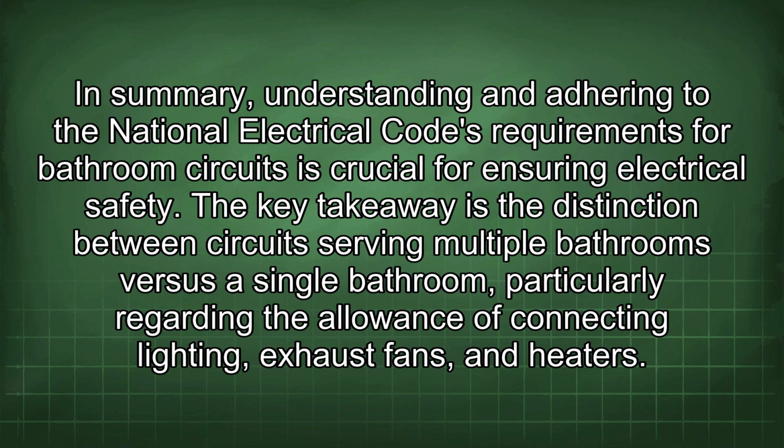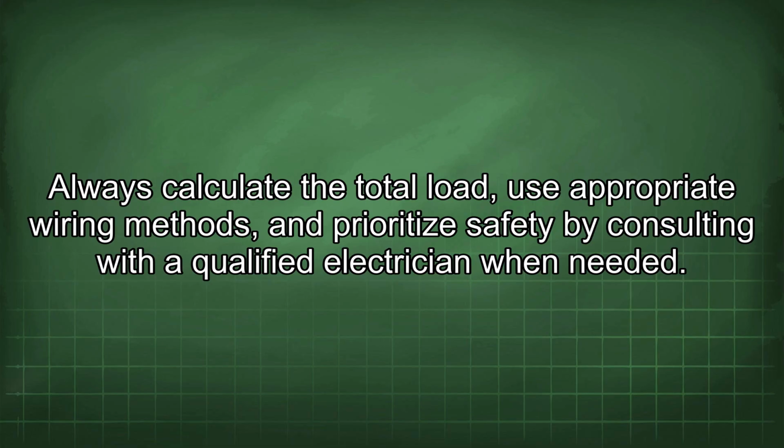In summary, understanding and adhering to the National Electrical Code's requirements for bathroom circuits is crucial for ensuring electrical safety. The key takeaway is the distinction between circuits serving multiple bathrooms versus a single bathroom, particularly regarding the allowance of connecting lighting, exhaust fans, and heaters. Always calculate the total load, use appropriate wiring methods, and prioritize safety by consulting with a qualified electrician when needed.